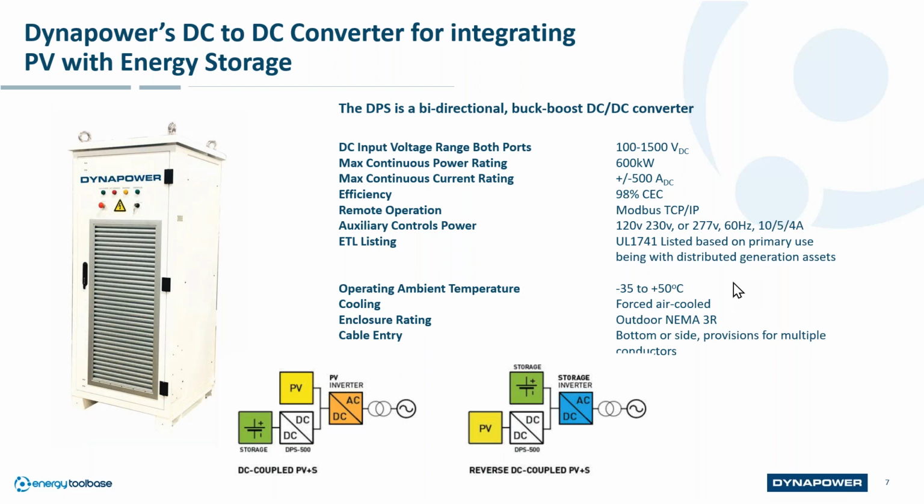And both of those outputs are then connected to, in this case for commercial applications, the MPS 125 EHV, which is the inverter that was on the outside of that package that we saw in the previous slide. So then all the energy coming from the PV is captured either in the battery or supplied as direct current to the input of the storage inverter.